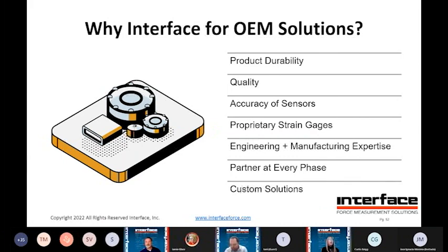But I wanted to know, what type of instrumentation do you frequently get asked about when you're looking at these types of designs? Is that something that we can also play a part in? Actually, yeah, it's a great segue into the next webinar, just in that around OEM in particular. Much more often, it's a win-win not only for us, but the customer to take the signal conditioning on board with the sensor. Essentially, what you can get is more repeatable standardized outputs. It's plug and play on the machine side. You don't necessarily need to go in and do any sort of calibration at the system level after you install the sensor.